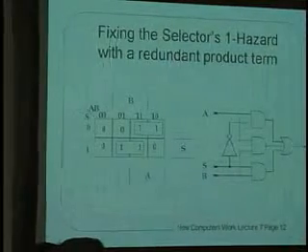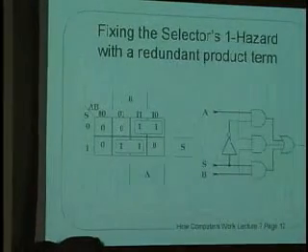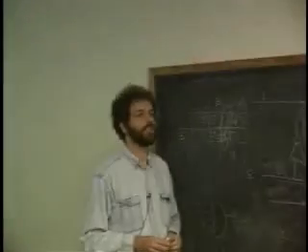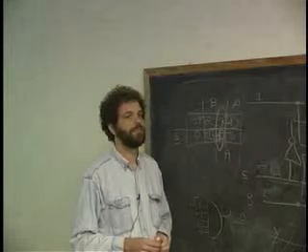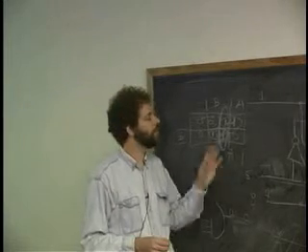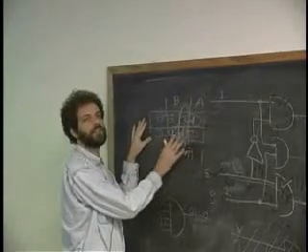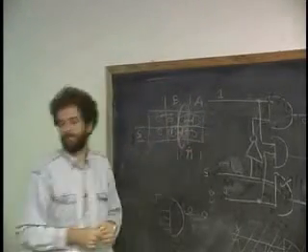So if you switch the switch, this is hazard-free. If you leave it on B, or B determines, you switch B from a 0 to a 1. It's actually hazard-free for everything. That's also hazard-free as long as it's a 1 input. If only one of the inputs changes, I don't need to know what these 3 things are to tell you that this is a hazard-free circuit.